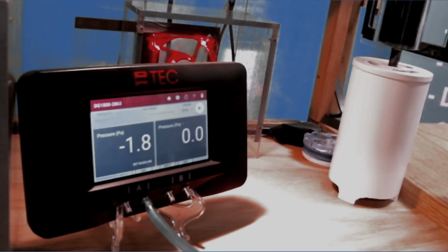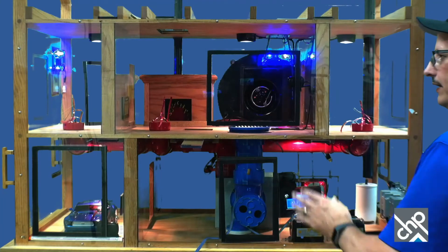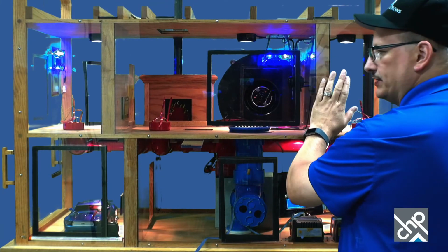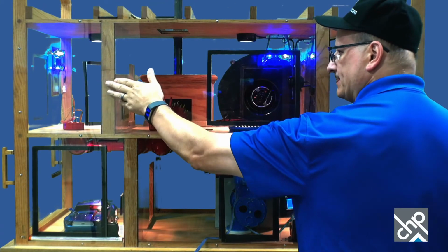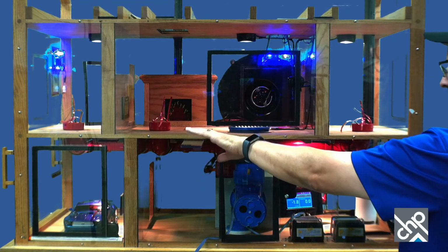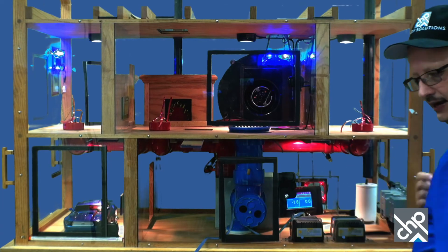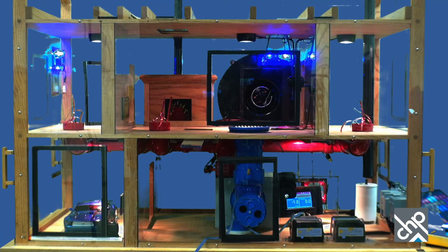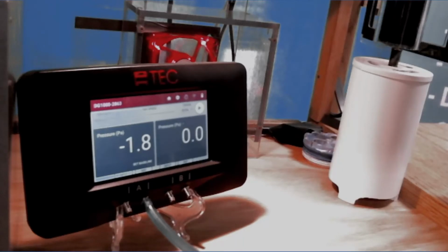Now, we are at the point where this door stays closed because there's no fans behind it. This door we opened, we tested, smoke went under, made the CAZ worse. Now this is our CAZ door. So our first number would be with this door open, and that's going to be negative 1.8 is what we have there.